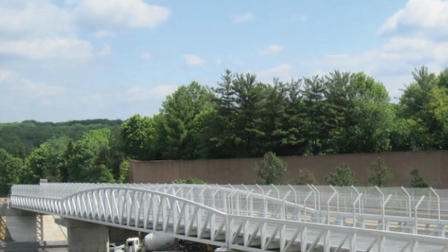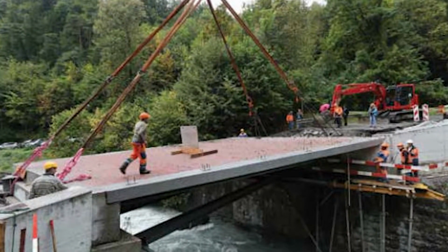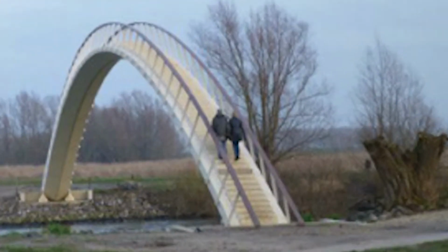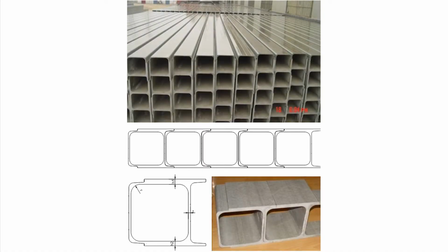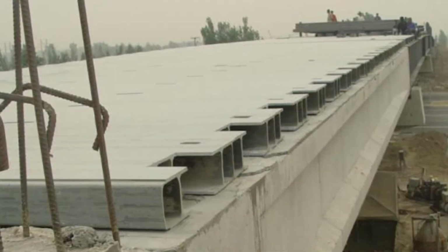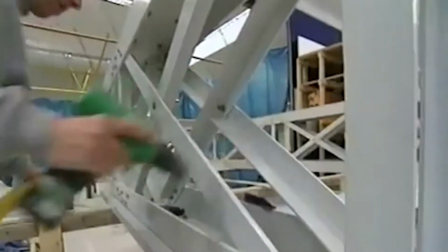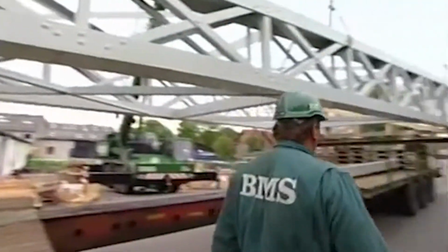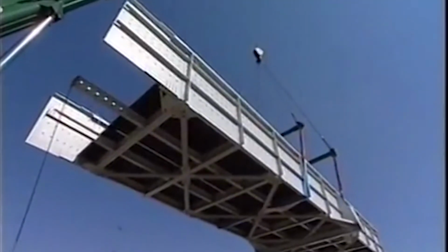There are quite a few examples of composite bridge construction throughout the world. These range from replacement of bridge decks to the construction of new bridges entirely from composites. Several companies have developed modular pultrusions that can be joined to create bridge deck structures. Entire bridges have also been replaced with complete FRP structures, especially in Europe.